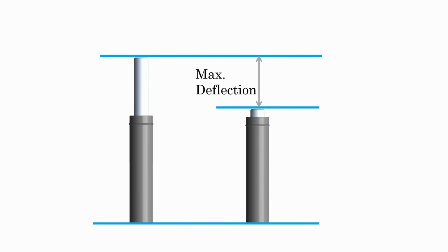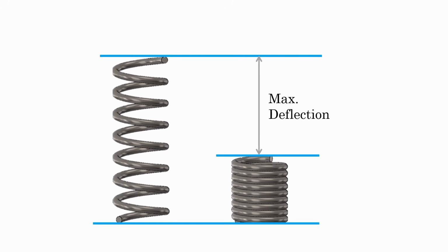Now, the gas spring, on the other hand, provides an almost constant force throughout the pressing stroke. At the starting, a gas spring delivers like 80% of its full force, and it reaches 100% when it's fully compressed. Whereas a mechanical spring goes from 0% to 100%, which is not ideal for the deep drawing process. So for heavy drawing process, gas springs are a better choice as compared to mechanical springs.